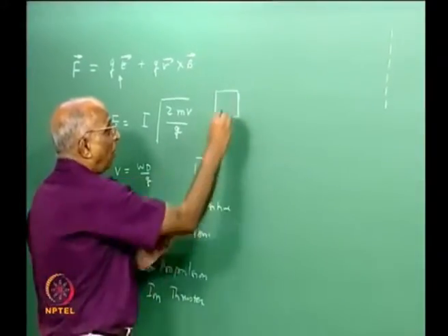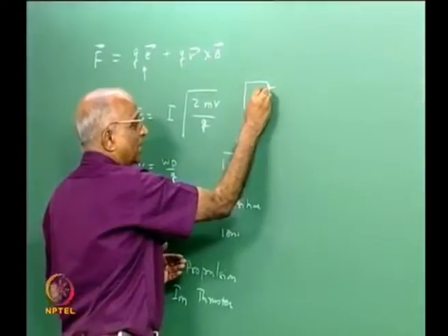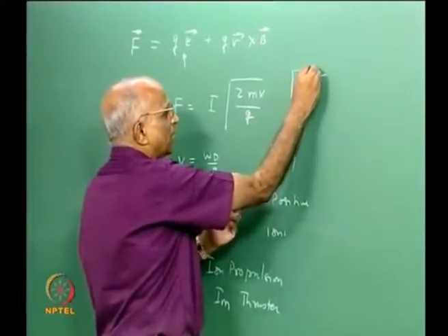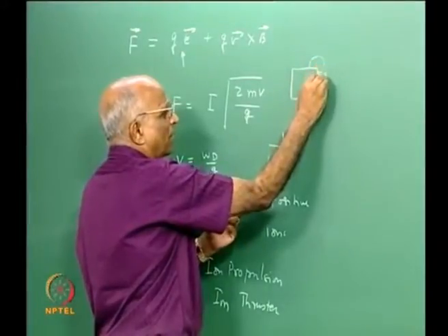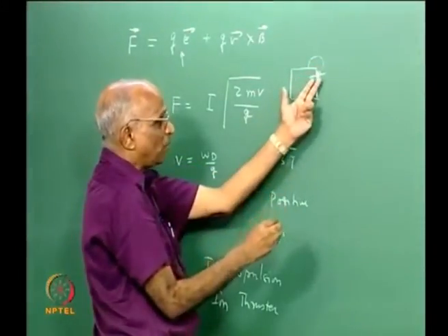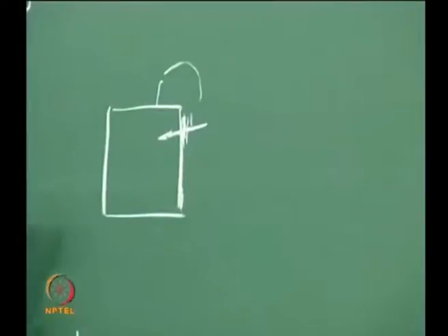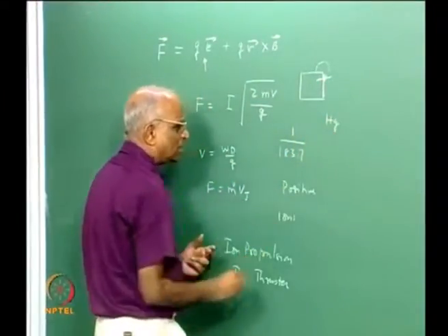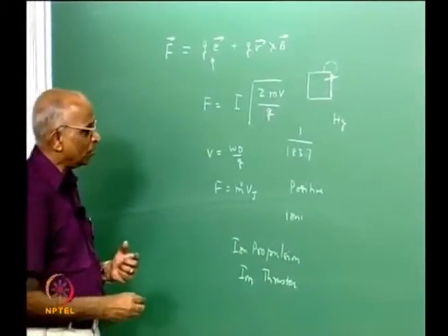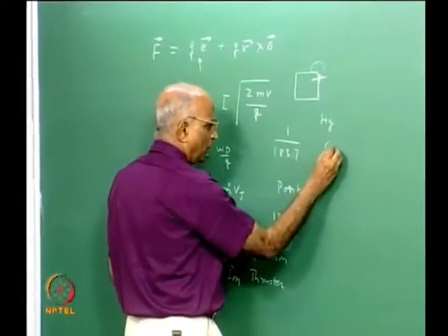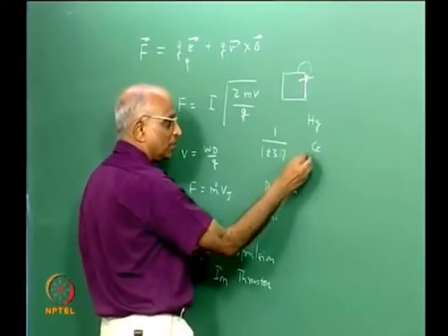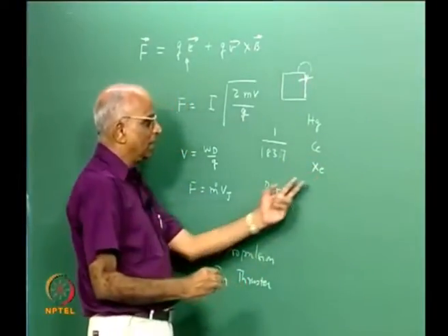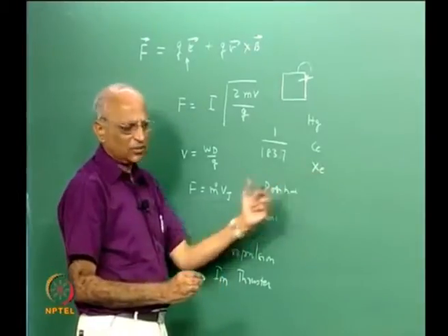They consist of optical quality glass which gets the radiation from the earth, and if mercury is let off from the spacecraft it will go and form a monolayer on it and make it opaque, and therefore mercury is generally not used. It was used in the earlier spacecraft and is no longer used. Cesium was also used but no longer, because it is a reactive metal, and what is universally used today is xenon, which is a noble gas.